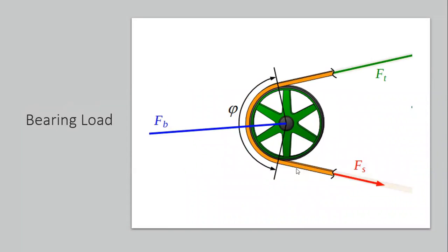And the last one we would go over today would be bearing loads. Of course, it's another rotation application, but the only difference here is that it's focusing on the forces being caused by the belts, because when you apply a belt to a rotating object, you try to extend it as much as possible so there's no slippage, and you want friction forces to do most of the work.